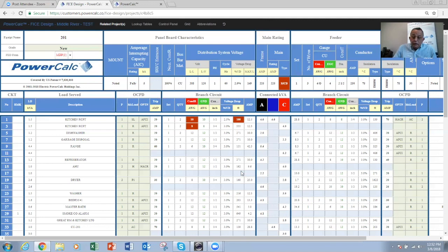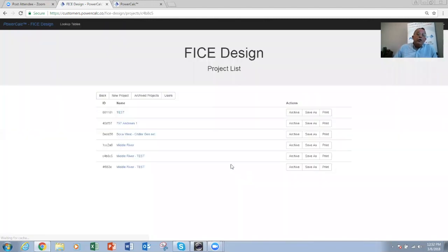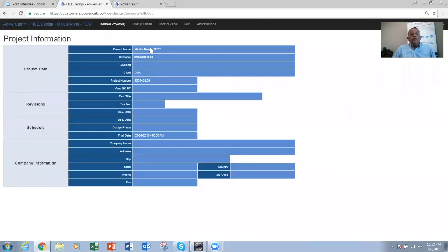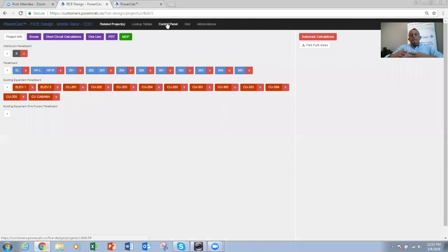And as I said, it's not a code requirement. I think it's going to become a code requirement, since we'll start seeing it required by the energy code, to perform the voltage drop. I can see it coming probably in the next cycle of the NEC. Can you imagine how much energy we'll be saving if we are losing about 4 to 7% of the delivered power to each piece of equipment? And if you look at how many pieces of equipment I have, that's a lot of money. Then go on to the application as a building, and how many buildings you have in the town, and in the state, and then worldwide. So it adds up a lot. So you're going to see that become mandatory. Any other question?